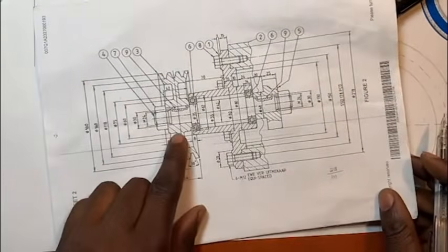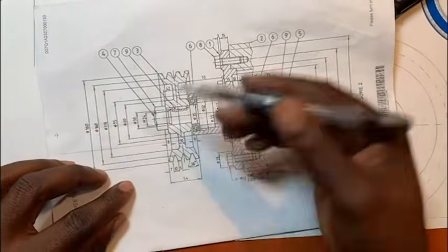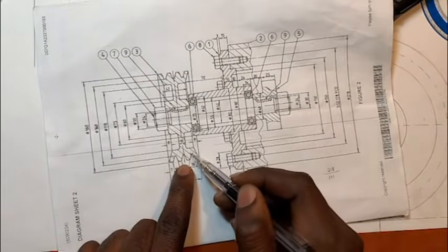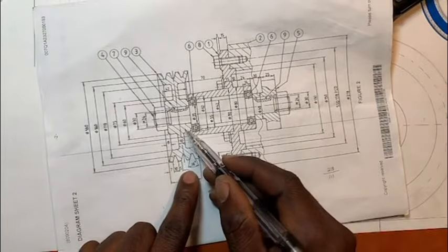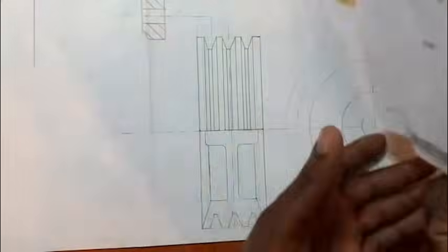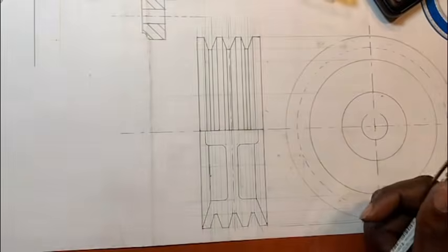Now let's double check again. They said with the bottom half in sectioning, or not with the upper part in sectioning. So if it's going to be with the bottom half in sectioning, this is what is going to be left, and your hatches go up until right here. So the upper part, we left it. Remember, I would like to emphasize the question: a half sectional front view with the bottom half in sectioning, not the upper part. So an outside left view, which means it's supposed to be like this. You get what I'm trying to say?